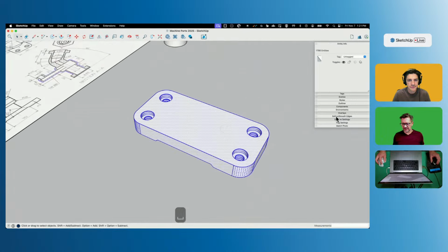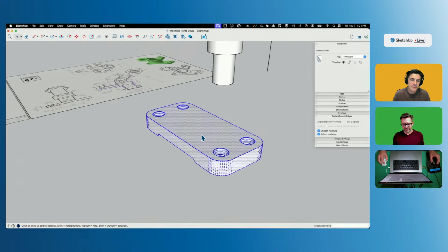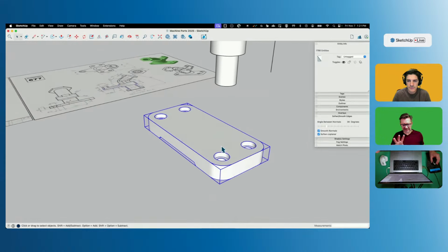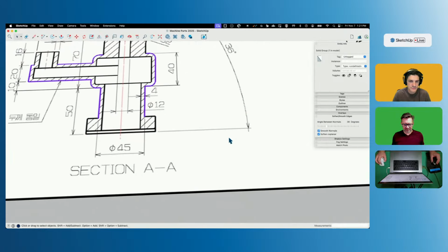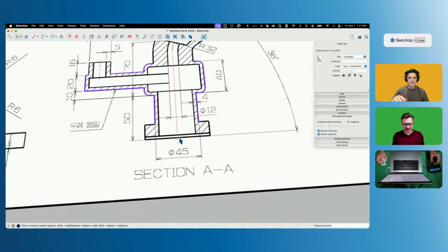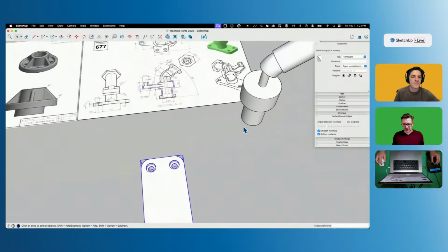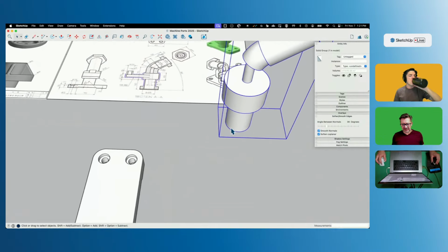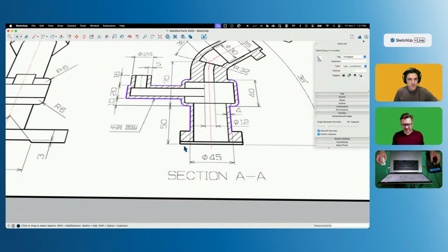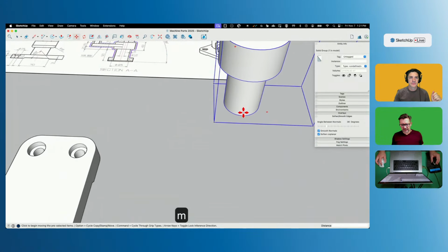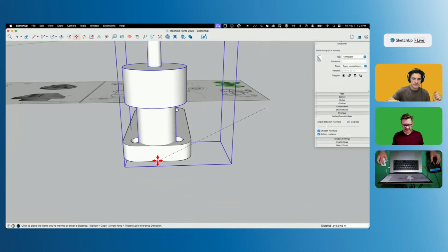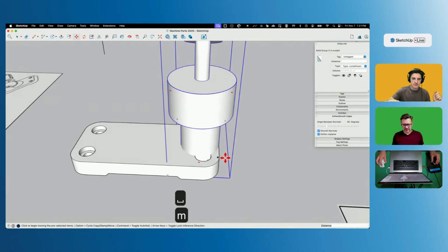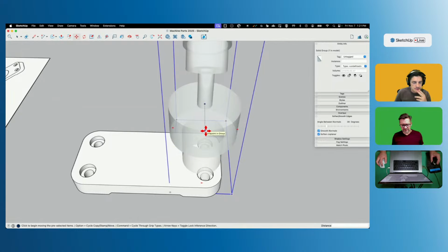So I'm going to triple click, clean it up real quick with soften and smooth, and then make it a group just to isolate the geometry for the time being. Now, I don't understand what this is. Oh, that's the little alcove inside. Okay. So if I take this, I actually ran this dimension from all the way to the base, so I would want to take this all the way down here. And then we'll scoot it over.